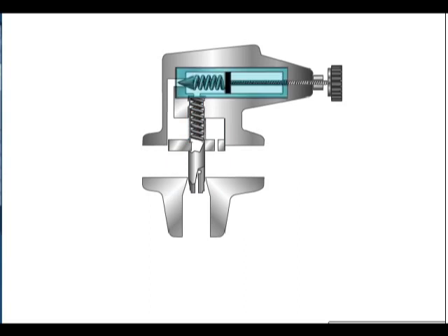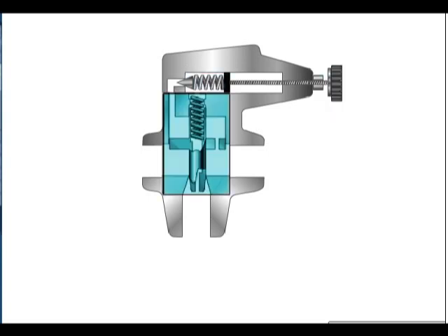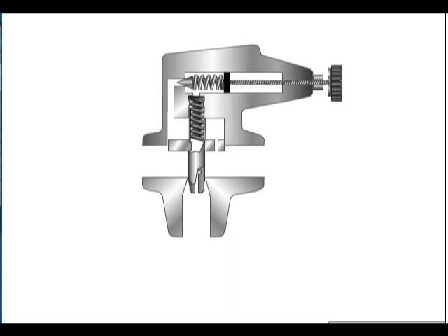The first stage is a small direct-acting relief valve, usually mounted as a crosshead on the main valve body, and includes a poppet, spring, and adjustable knob. The second stage handles full rated flow to the tank. The first stage controls and limits pilot pressure level in the main chamber.